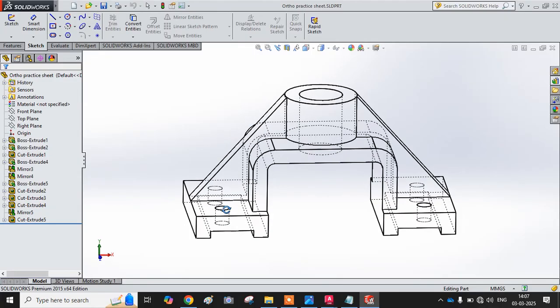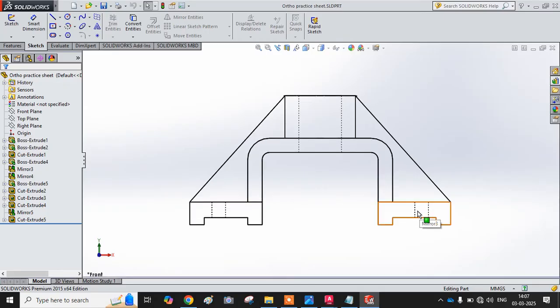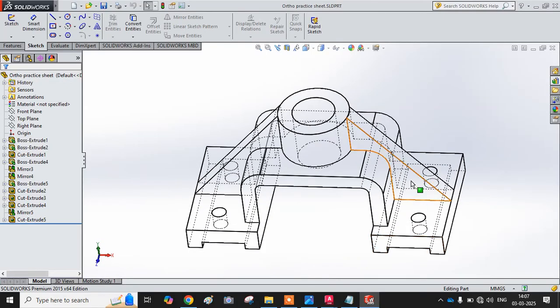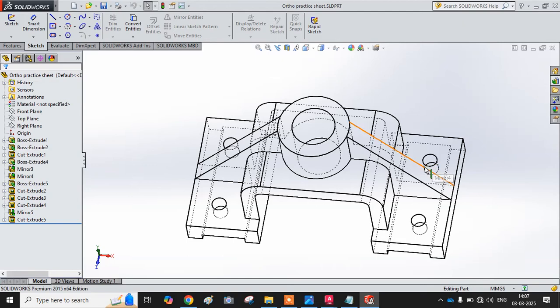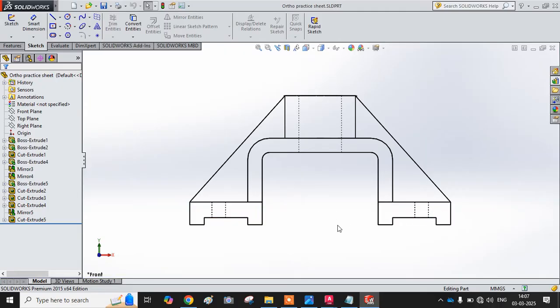This is the front hole. Same way, there is a hole at the back also, right? Here you can see one hole is there, but on the back side of this rib there is one more hole. Both the hidden lines will be overlapping. So in the front view, actually you are looking at only two holes, no? But there are four holes. And from where will it be clear that there are four holes? When you see the top view. In the front view you will see only two holes.